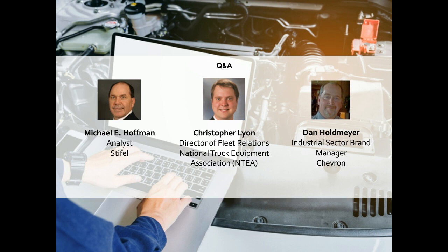And I guess one of the biggest things too is make sure that they can deliver on time, which is a big critical success factor. And finally, if you're looking at keeping your hydraulic systems running efficiently and a long time, make sure they deliver in a clean condition, meeting the OEM's requirements. Not everyone can do that. Not everyone will stand behind their recommendations or their products meeting that specification. You may pay a little bit more up front for the clean oil, but it's a lot cheaper keeping the dirt out versus removing it from the system itself. And it does create much longer life of those hydraulic components and much smoother operations for your operators out there doing the daily grind.